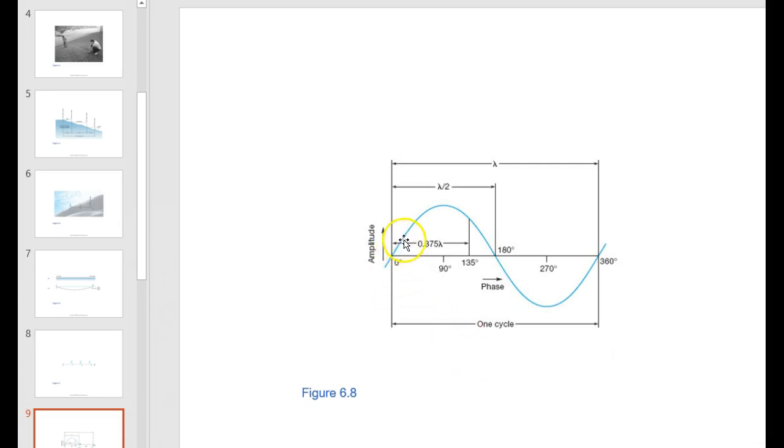And what that tells it is that the total distance between the prism and the total station is going to be some full number of wavelengths plus one partial wavelength that can be determined based on this phase angle. Now, obviously, for one light wave, one wavelength, there would be an infinite number of solutions to that. However, statistically speaking, if you send out approximately 7 different light wavelengths, you will come up with one unique solution, or sometimes 2 unique solutions that would satisfy all of those equations.